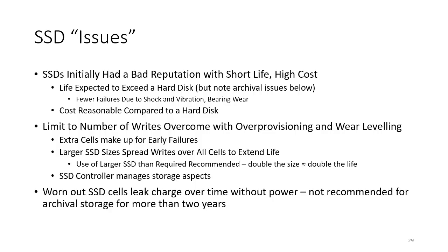Again, the cost of SSDs is coming down. So if you think you need 128 gigabytes, buy a 256. But if you're going to do that, think about the cost of ownership over the long life cycle of an industrial PC. You might say, well, let's go for 512 gigabytes. Even if you don't need it all, having that extra space will help you with that wear leveling and significantly extend the life of the SSD.